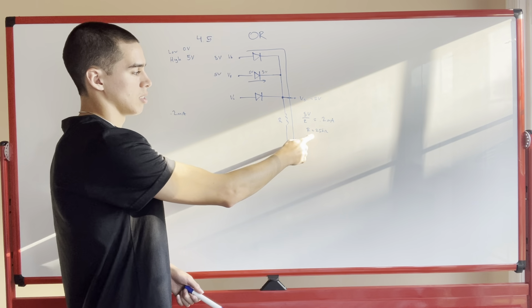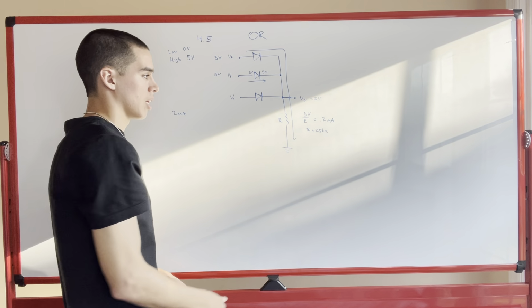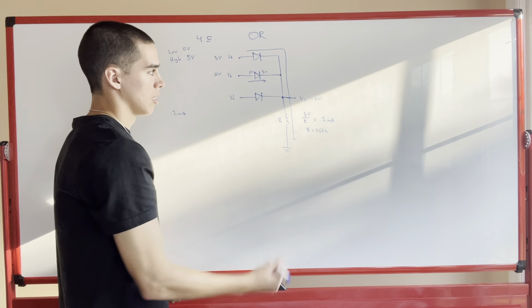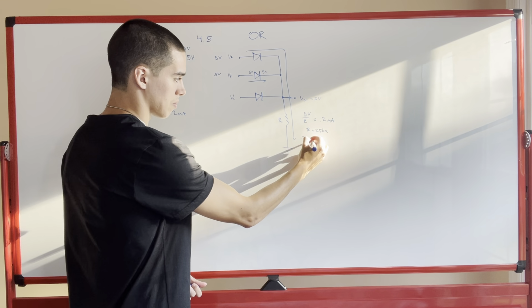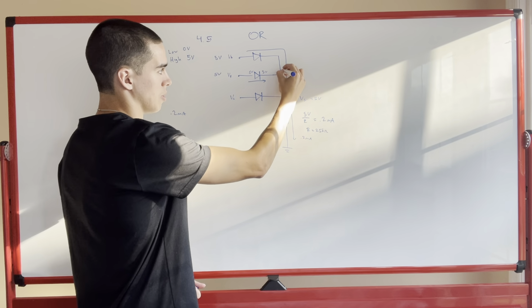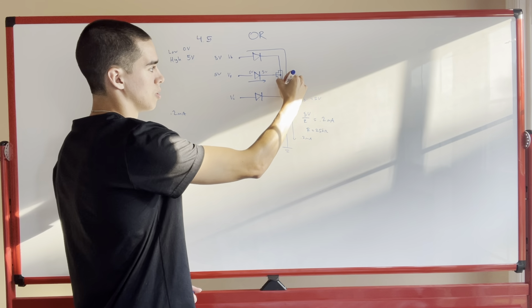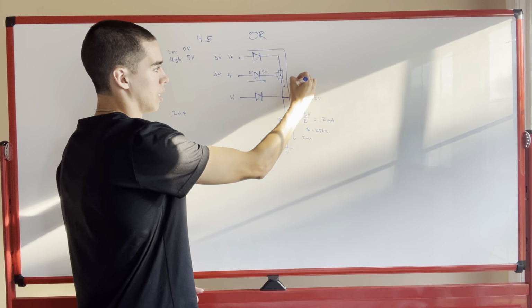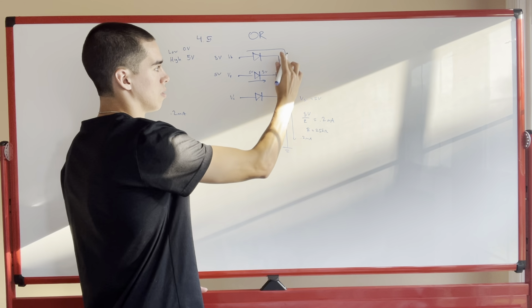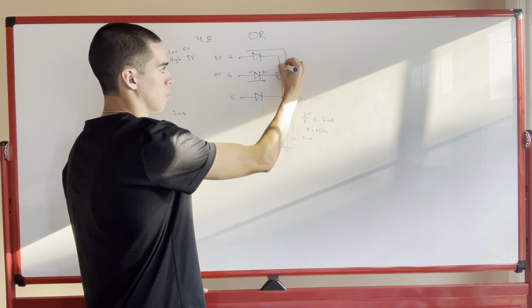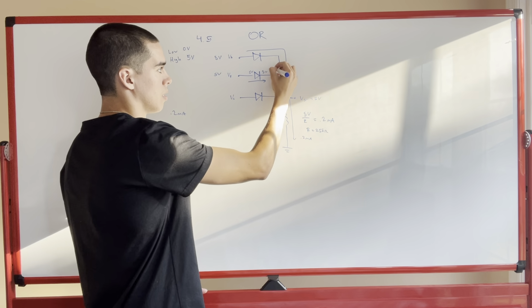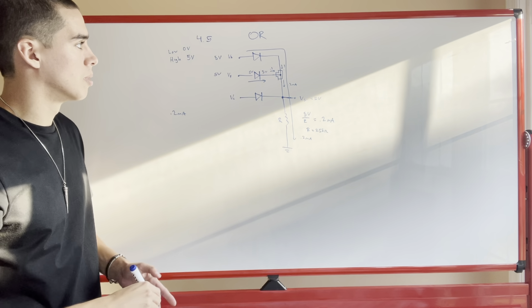And if the resistance is 25 kilo ohms, we're still going to get 0.2 milliamp current going down here, right? And now that 0.2 milliamp current would split here. We would have 0.1, 0.1, right? We'd split the current between those.